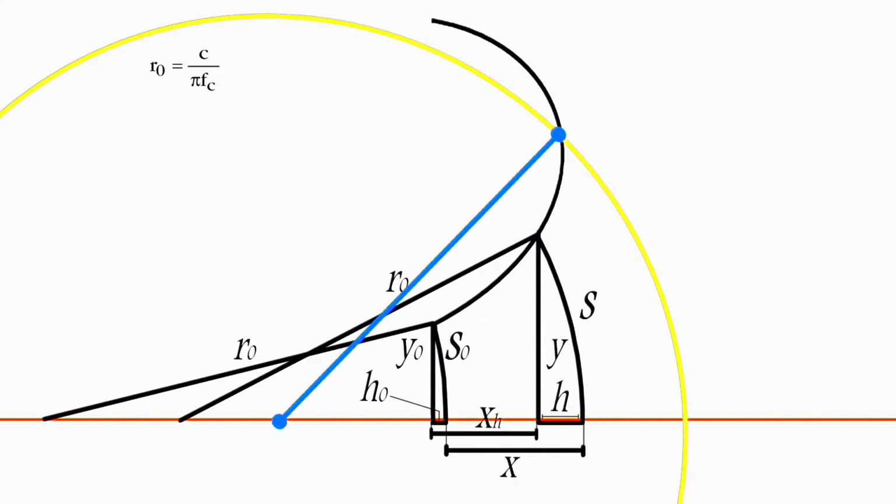Rho is the constant radius of the wavefronts, and as you've seen, the horn was shaped according to that. Yo is the driver radius, and Ho, or the height of the wavefront at the throat where the speaker is mounted on the horn, is calculated by a simple formula. We don't need to keep these formulas in our mind, but for better importing into Excel, we should know what the parameters are. M is the growing factor and is given as.